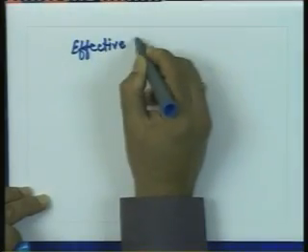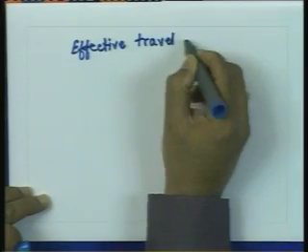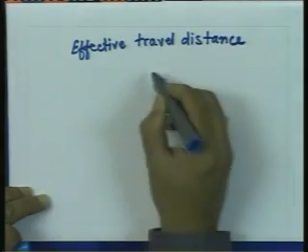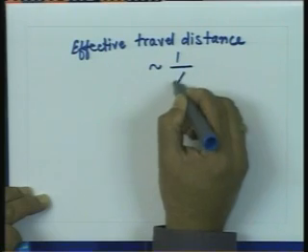One can then say that a distance of 1 over alpha tells you over what distance the wave effectively is going to travel, because the wave amplitude is going to reduce to 1 over e of its initial value over that distance. So, we can have something called an effective travel distance on the line, which is of the order of 1 over alpha.